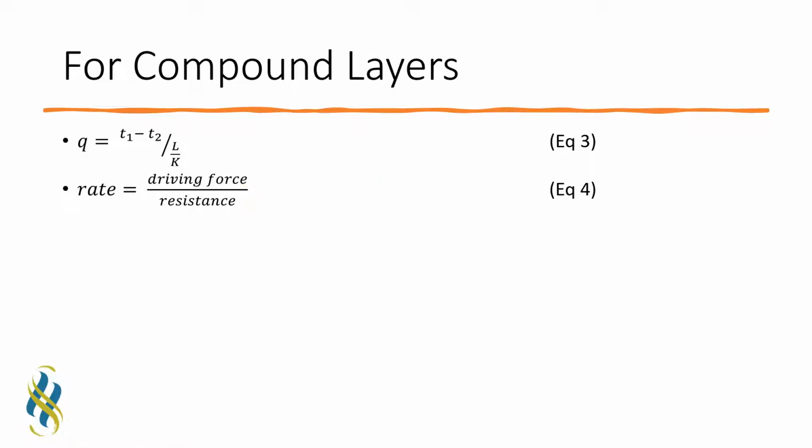The temperature difference is the driving force of the heat transfer, and it will be realized that the resistance to conduction will increase for greater thickness and will decrease as the coefficient of thermal conductivity increases and as the area becomes larger.